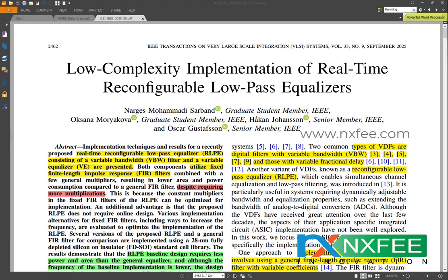of control parameters. While this approach is flexible, the existing hardware implementations often rely on general multipliers and frequent coefficient updates, which increases the hardware complexity, power consumption and delay. This makes them unsuitable for real-time processing of time varying signals such as chirp signals. These chirp signals have a continuously changing frequency and therefore require filtering architectures that can adapt efficiently while maintaining a